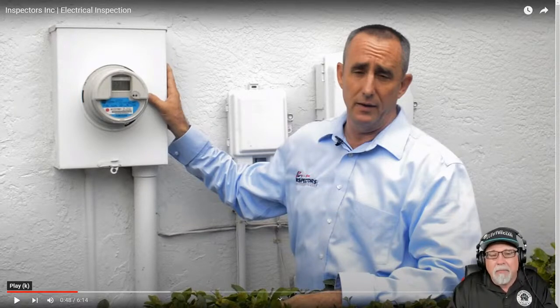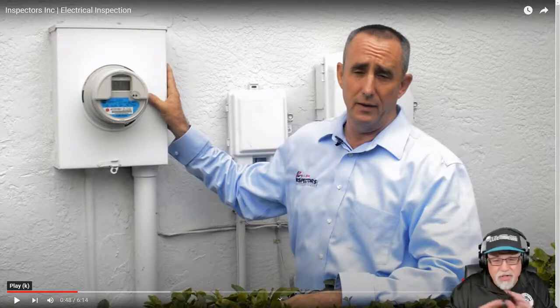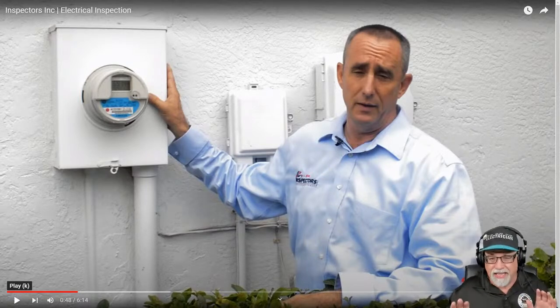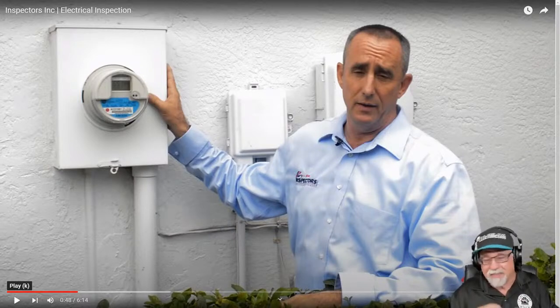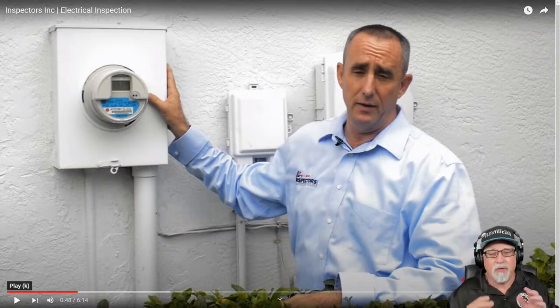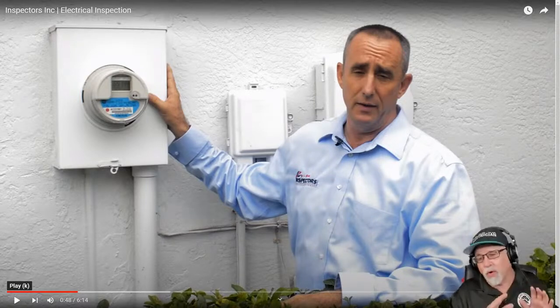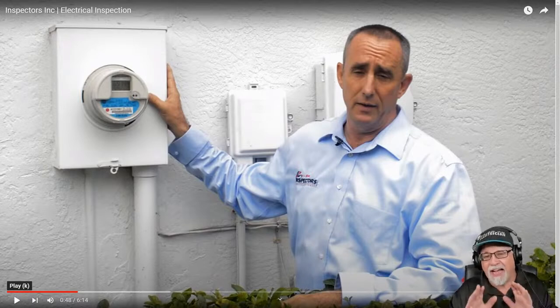Now, because the building has metal piping in it, that has nothing to do with whether or not it's a grounding electrode system. It has nothing to do with that, okay? So get that out of your mind. You have to bond the water piping inside of the building, but that has absolutely nothing to do with it. And yeah, the bonding of the water piping is 250.104(A). That's the water piping bonding. That's in Part 5 for bonding of Article 250.